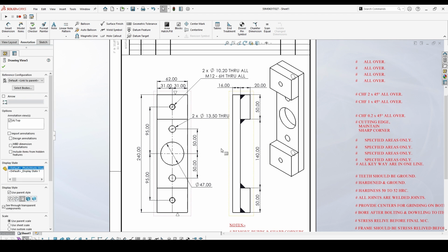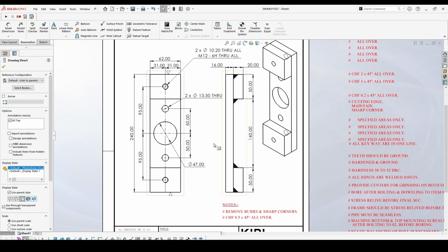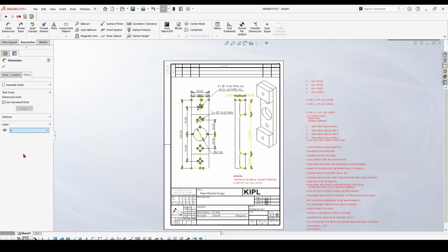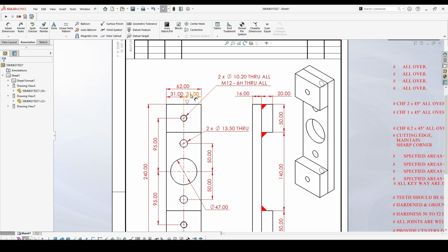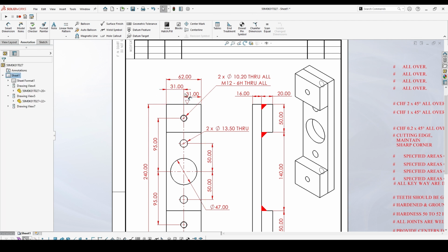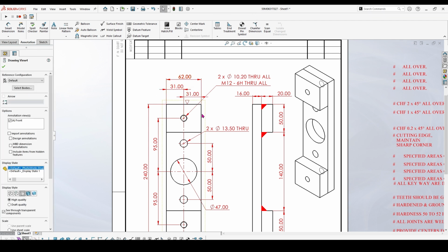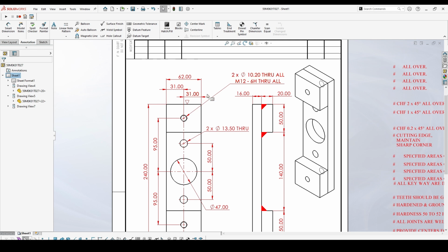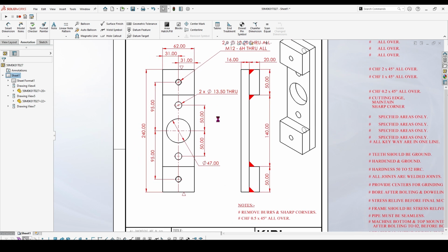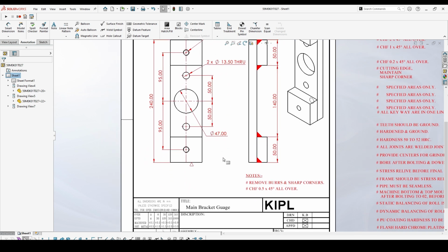This is a small drawing, so I thought of explaining it to you. That is a small mistake people do. Okay, this is what it is. And one more last point, I would say I'll try to put dimensions in red color. Why? Because these dimension lines clearly show that this is the dimension, and this is the object line, separately. So it will help the person who is reading the drawing. So it will clearly differentiate when it comes to dimension lines, right? This is how I do it.